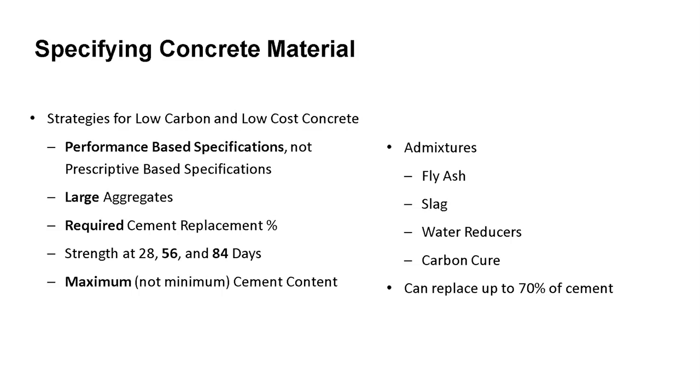In the past, the engineer would specify exactly how much cement, exactly how much rock, everything that would go into the mix. We rarely do that anymore. But another thing we consider in our specs are the size of the aggregates. We'll use larger aggregates on foundations and areas where you have lower cover, or you want to get maybe lower cost also.